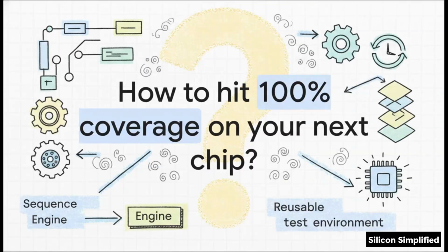So as you architect your next verification environment, really ask yourself, how can you leverage this sequence engine to build smarter, more reusable tests? By mastering the body task, the execution handshake, and reusable virtual sequences, you are essentially building a bulletproof verification environment. The beauty of UVM is that once you've mastered this flow, there is virtually no limit to the complexity of the stimulus you can design.